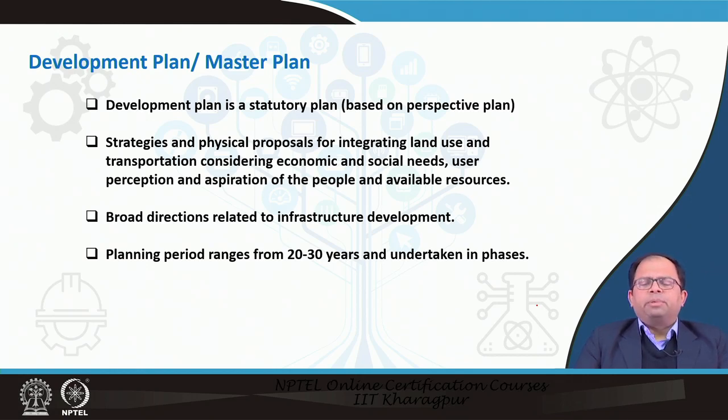So if the city already has a perspective plan, the development plan will definitely be guided by that. But it is not only the perspective part; we not only look into broader proposals for that particular area, but we actually develop strategies and physical proposals for that urban area. For example, we will divide certain zones in the area, we will reserve certain areas for certain land uses, or we will divide the city into different kinds of land uses. We will say that in this area you can develop residences, in another area you can develop commercial, and depending on a strategy that we have to develop this area in a sustainable way, we will adopt different measures. So this is where we integrate land use and transportation in the planning process.